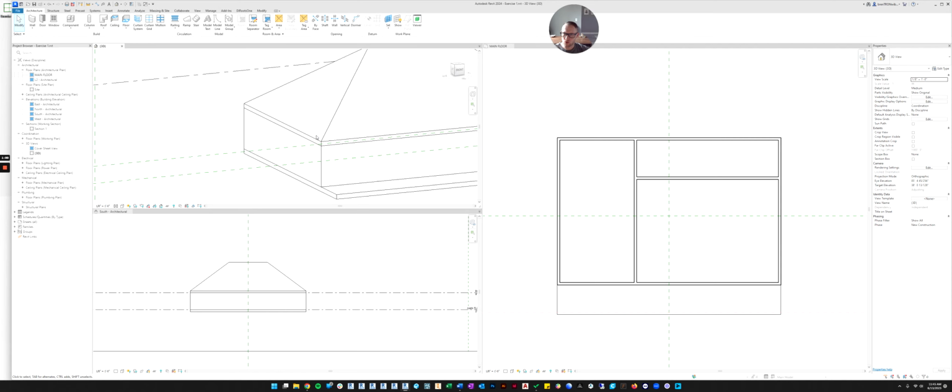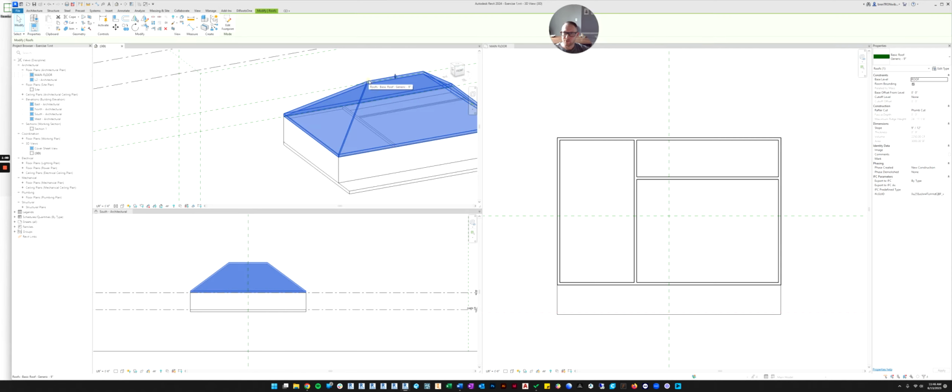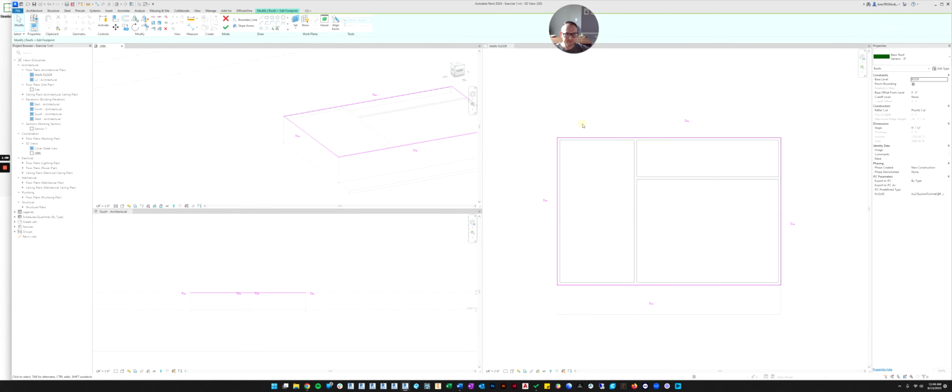The only problem is normally the roof overhangs the edge of the house. So let's figure out how to do that. Let's go back, edit the footprint. This is where the offset command could come in handy. Let's go to the offset, and right here, let's enter 1 foot. Now, if we go over here, click once to activate the view. Once you've activated the view, you can select each line individually and offset it, or if you hover over it, you can hit the tab button and you can see it will do all 4 at once. So now it offsets those lines all at once.